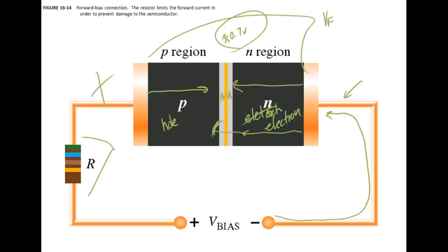When we get up into the forward bias of this, it's going to depend on the diode and what it's designed around. But it is going to drop a voltage, and it is going to have an R, which means it could get hot, right? You understand? So these diodes are going to be rated at a maximum current. If you get above that, it could do what? It could burn it up. So if I need to go to a higher current, what am I going to have to do with my diode? I'm going to have to make it bigger, right?